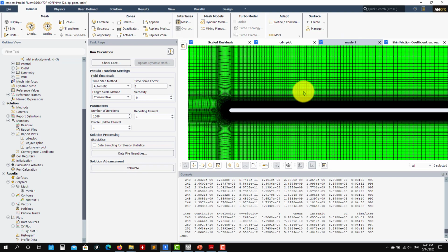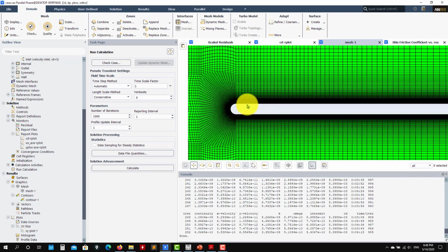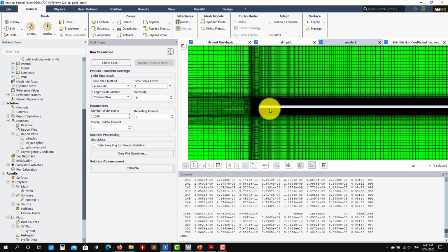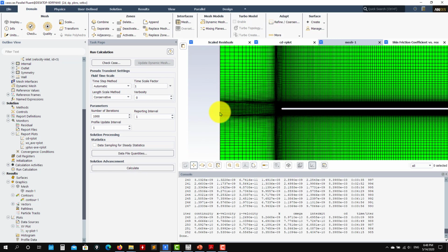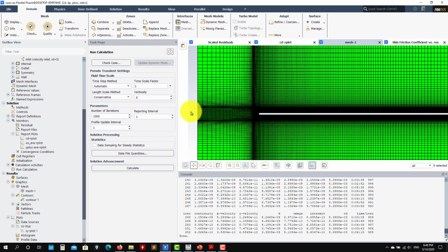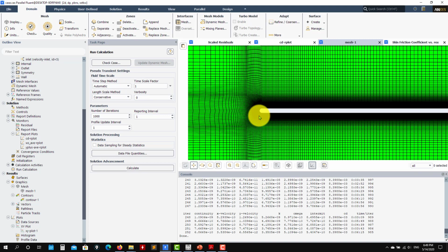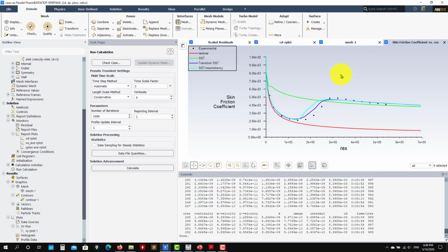To resolve transition to turbulence, you need to verify measures such that you have y plus less than 1. Also, you need to be careful when imposing boundary conditions, so we're going to address that in this case. You need to give boundary conditions and some variables, but you need to let the turbulence intensity decay, so you have the right decay and can capture the proper physics.